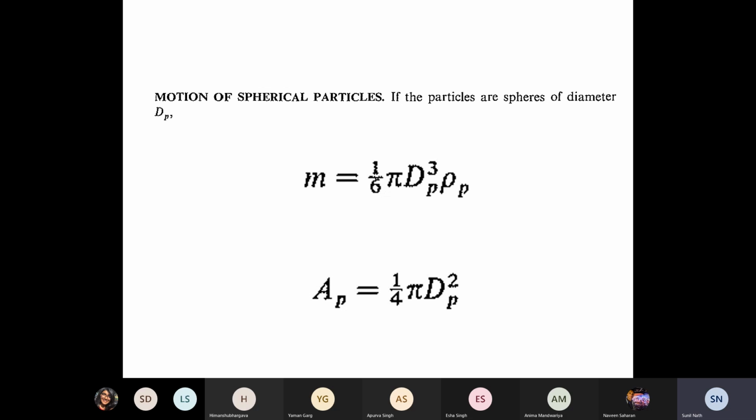So the friction factor was 16 by Re or 64 by Re, but when we have the drag coefficient CD, it was 24 by the Reynolds number. Okay, that is what it was for creeping flow of a sphere. So now you can take this general expression, which is valid for a sphere at any Reynolds number, for any flow dynamics, and limit it to the case of the creeping streamlined flow.